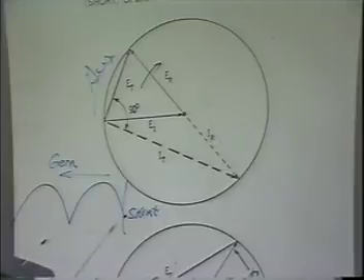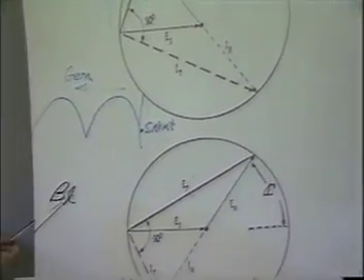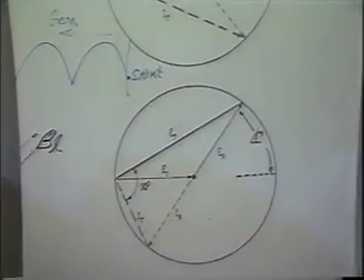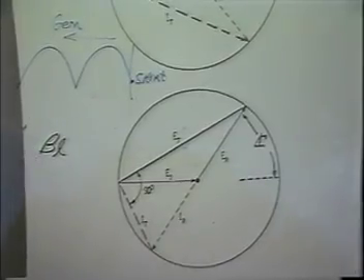Now, if you remember correctly on the transmission line, we had a distance called beta L. If the phase were 3 degrees per centimeter, and it's 10 centimeters, you'd have 3 degrees times 10 centimeters, or 30 degrees. That means that every 10 centimeters, the wave phase changes by 30 degrees. We looked at that previously on a diagram, went through it very carefully, didn't we? This is the phase constant. If you say that the phase is changing 30 degrees per centimeter, then every centimeter the phase changes by 30 degrees.